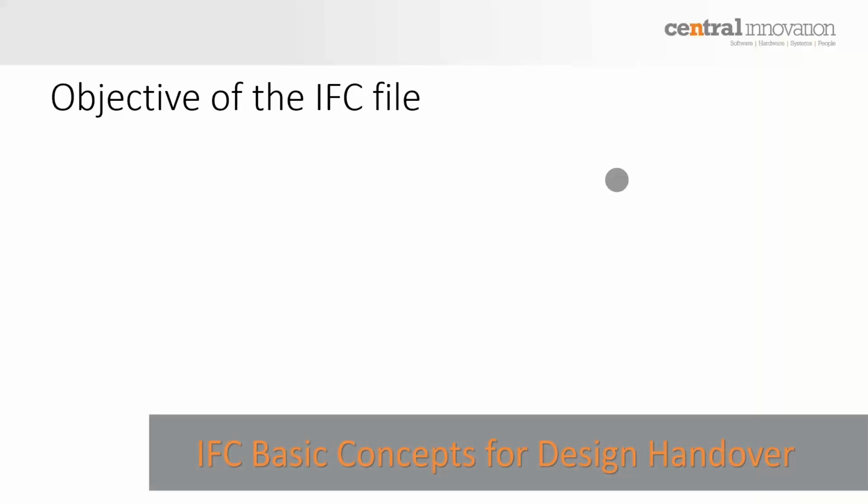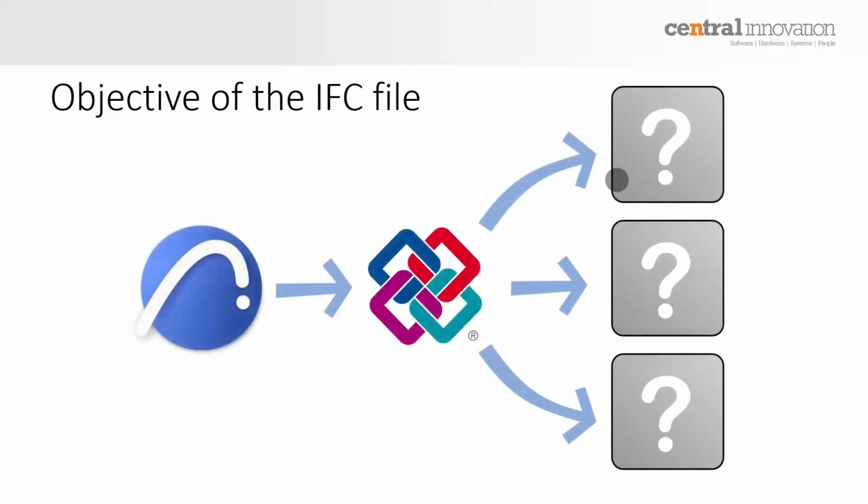All right, now getting into the topic itself. The objective of this IFC file that we're going to use today, unlike the typical exchange for coordination, where you essentially exchange a file and you're not 100% sure which software will be the receiving software. In that case, that IFC file needs to be set up in a way that can be interpreted by different pieces of software using the standard format and the standard schema within the IFC.